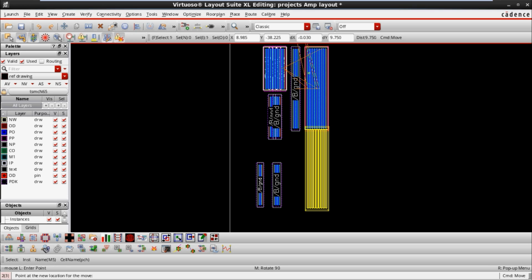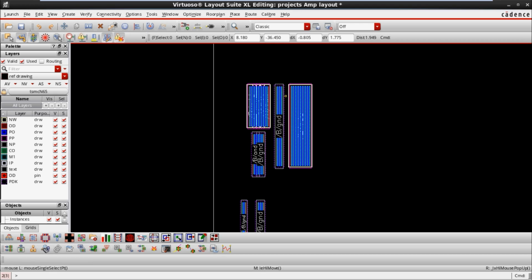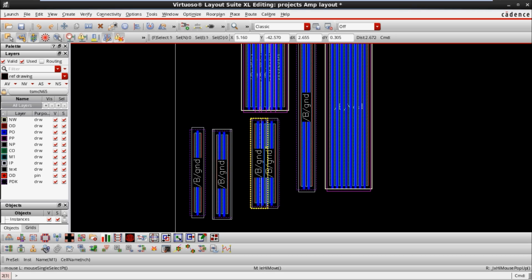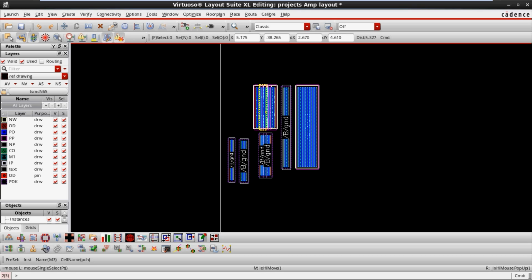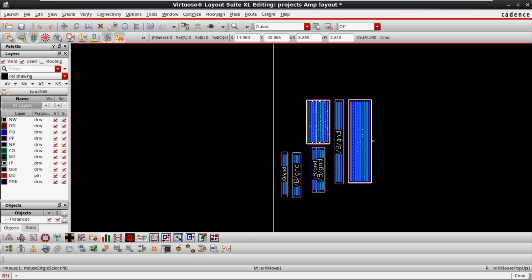So now I have converted these two devices into two different kinds of floor plan. See now we have this current mirror, and then we have the differential pair. Just I will keep the current mirror circuit here. See now, from the huge layout, I have shrunk the size from 19.6, because each and all the devices have different sizes. Size wise we have different kinds of size, which means W. I am denoting it as W. So W has different kinds of values.